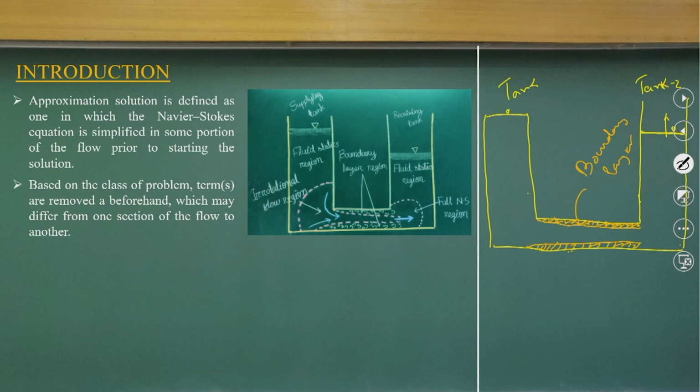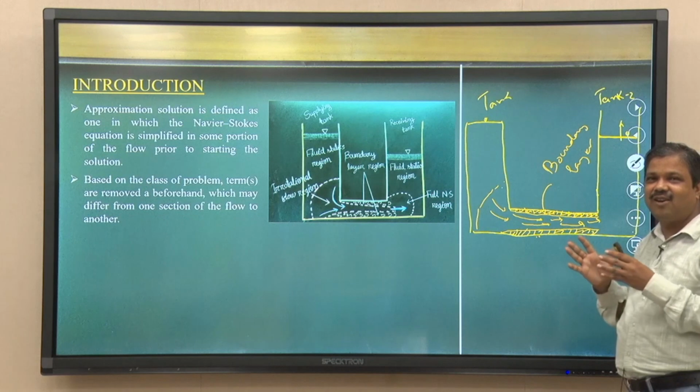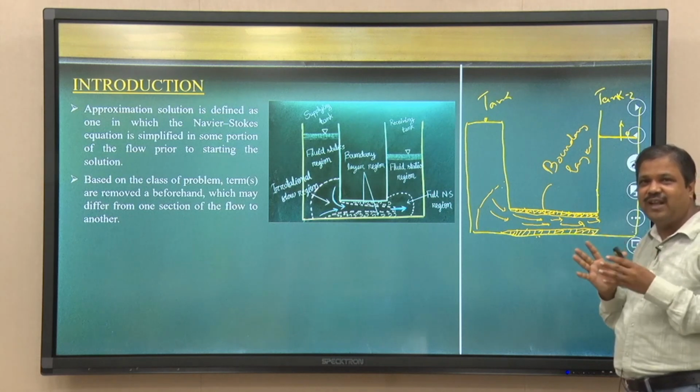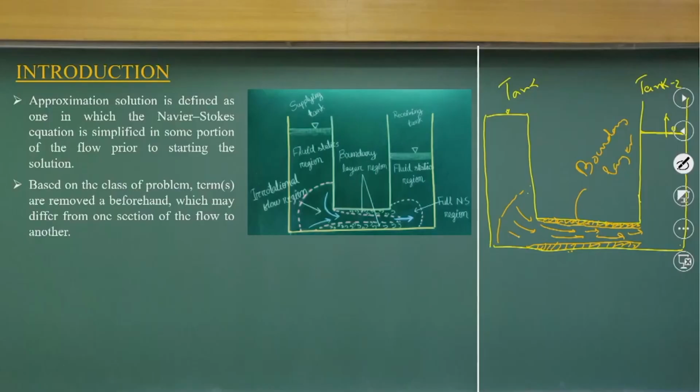The regions very close to the wall will have flow going like this, and the flow will go like this. So, in fluid mechanics you have to understand how the flow happens at different scales. It is not simple mathematics, so conceptual visualization is required. That means the flow in these regions will not have any rotation. These regions will have irrotational flow.